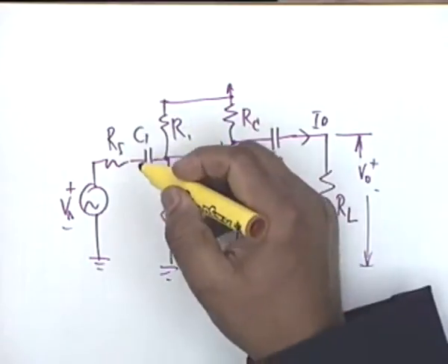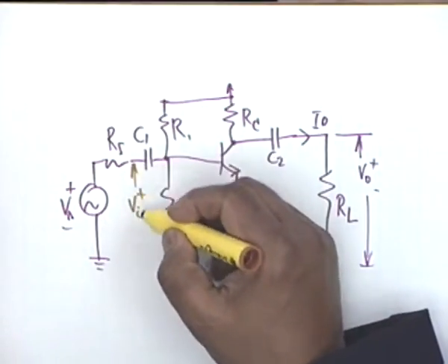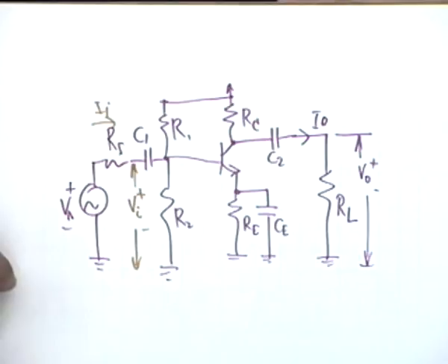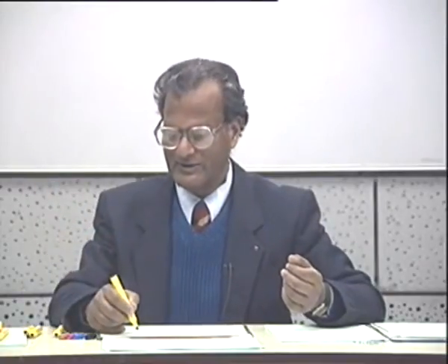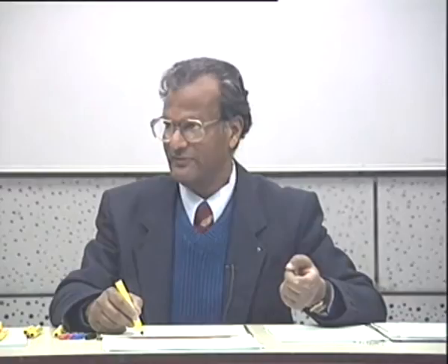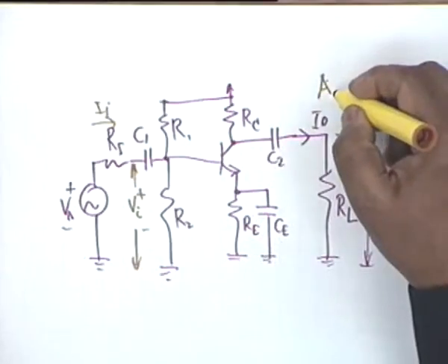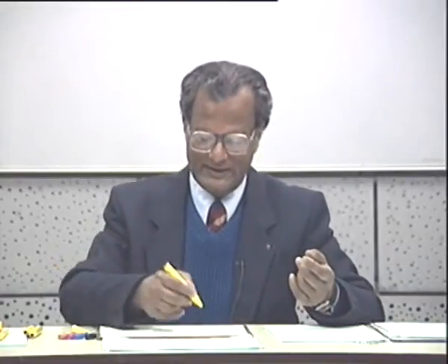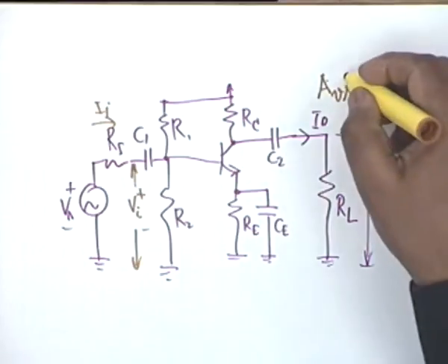This voltage is Vi and this current is I sub I. Once again we are interested in voltage gain, current gain, but the gain that we shall mostly be interested in now, which is affected by frequency, which is affected by capacitances, is more than AV, now it is AVS, because most of the sources in practice, whether it's a microphone or, let's say, a cartridge pickup from a record player or a CD-ROM player, whatever it is, there is an internal resistance, okay, and mostly we shall be concerned with this gain.